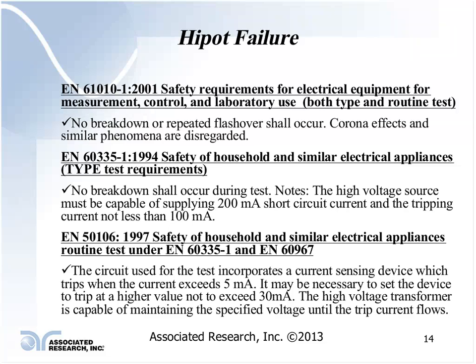So again, you want to make sure that the operators are fully aware of the hazards involved, that you are complying with OSHA standards in setting up a safe testing environment, that you guard anything against direct contact, and that you are wearing the proper personal protective equipment if you are dealing with exposed energized sources, this kind of stuff.